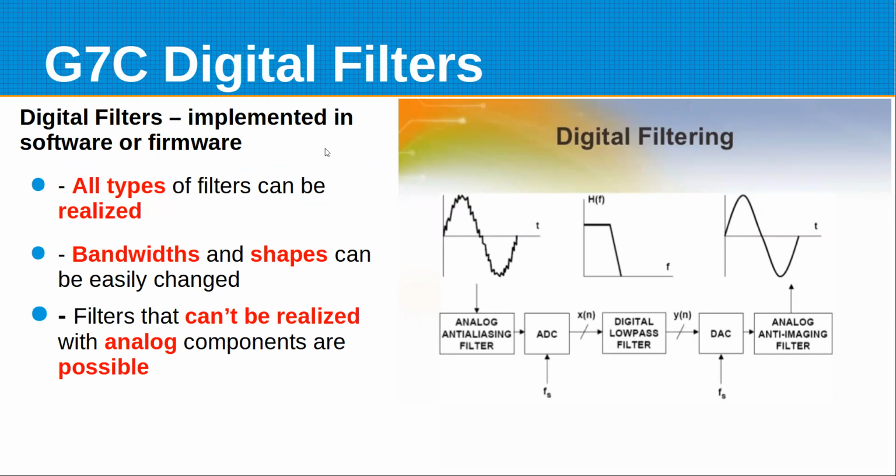A lot of them will have what they call passband tuning, where you actually have 2 bandpass filters and you can shift the cutoff frequencies of the 2 independently and have them overlap and get a very narrow passband, or shift it to one side or the other to eliminate some signal that you don't want coming in.